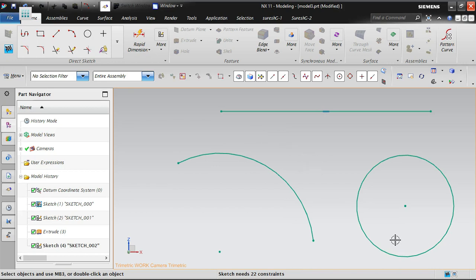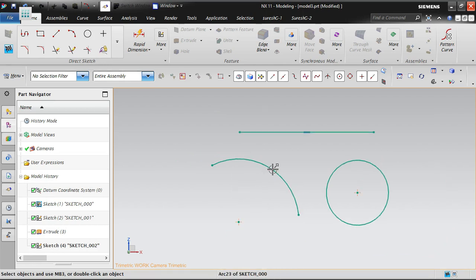The vertices means the line's end point, midpoint, and these are all the places where the line ends. Vertices means the line's end points and circle center point, and arcs' end points and center point, you will get some points. That is what vertices is. If this vertices is visible, you can select very clearly. Suppose you do not know where the vertices are, the selection of these snap points also is very difficult. So generally in the sketches these vertices will be in the on condition. If you do not want, you can switch off it also.